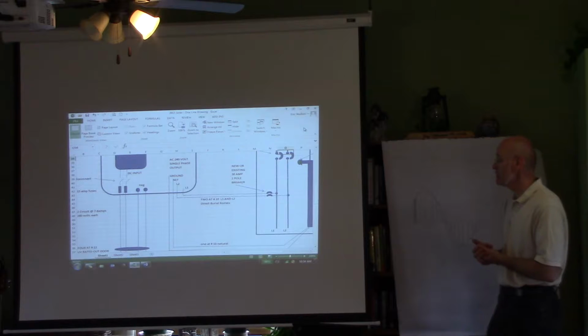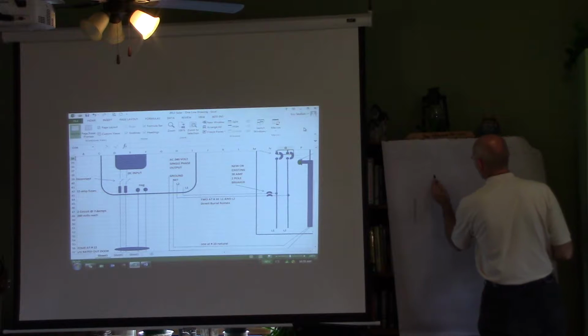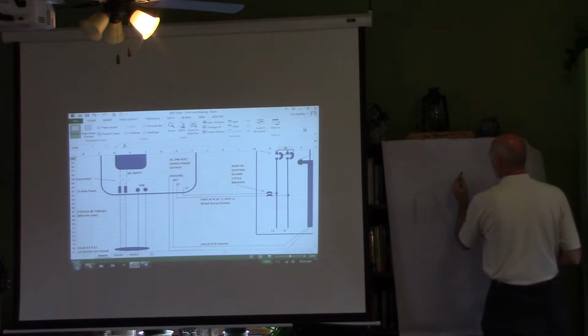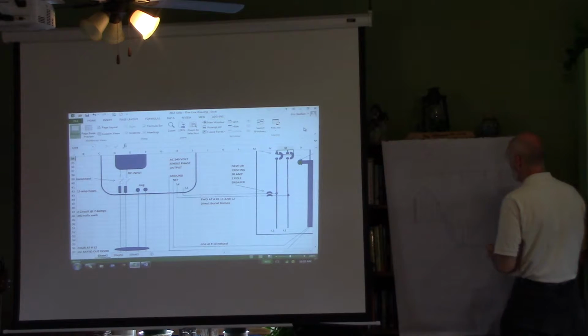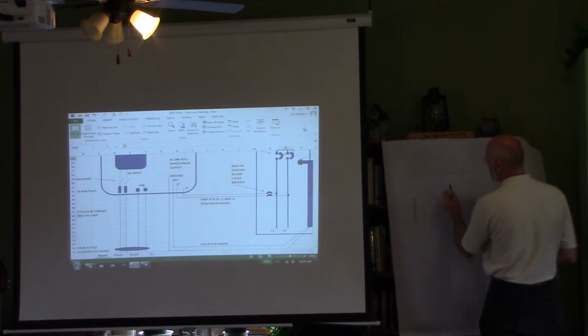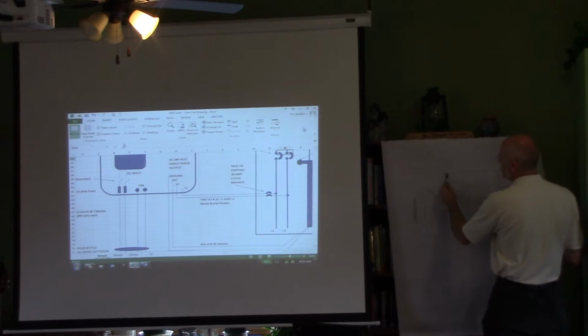The reason the safety standard is there is because if I got a line coming down the road here, and every little house has a transformer, and it converts it from 5,000 volts down to 220, and I got every little house down the road here, and let's say the semi takes out that pole. Oh, wait a minute, this guy over here, he's got solar panels. So the wireman comes out here, he puts up his ladder, and he's going to grab this wire and grab that wire, put them together, and tighten his hex bolts or his unions or whatever he's doing.